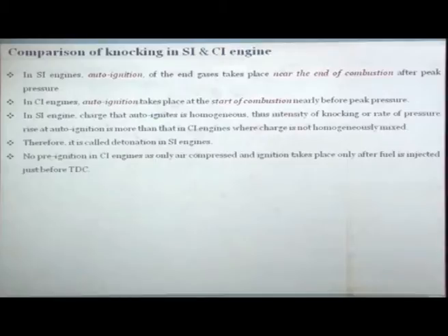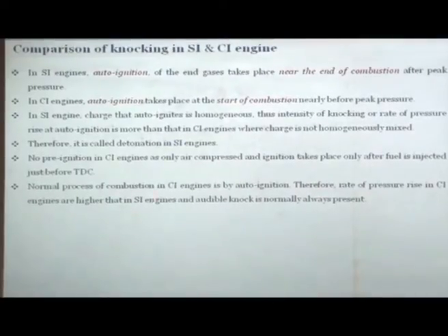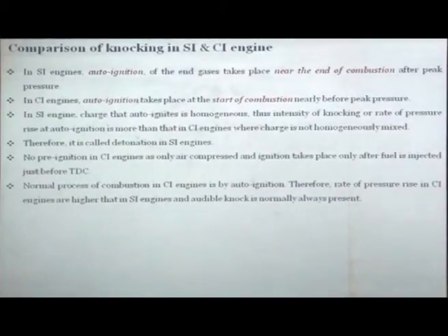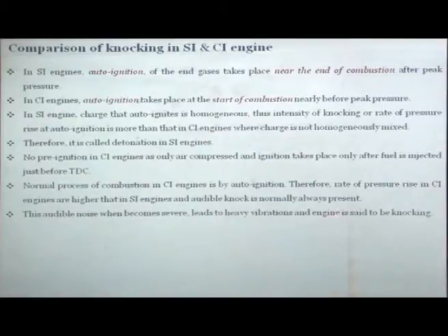The normal process of combustion in a CI engine is by auto ignition. Therefore, the rate of pressure rise in CI engines is higher than in SI engines, and audible knock is normally always present. When the audible noise becomes severe, it leads to heavy vibrations and the engine is said to be knocking. In a CI engine you always have hard combustion, which is why diesel engines always make much more noise than SI engines. But that is not called a knocking condition. When the hard knocking becomes so bad that the engine starts vibrating and it becomes abnormally painful, then it is called knocking.